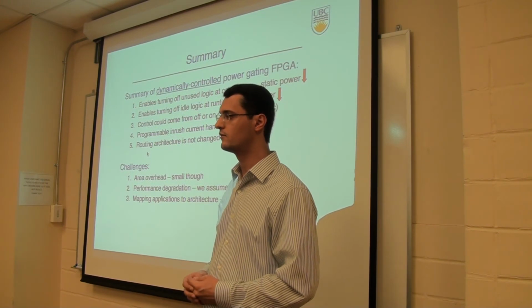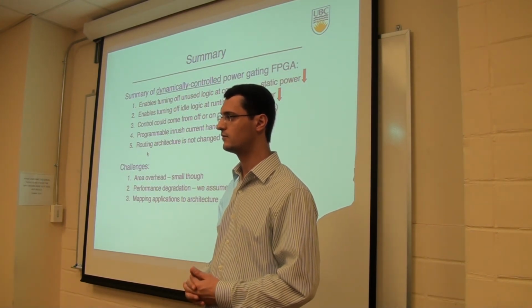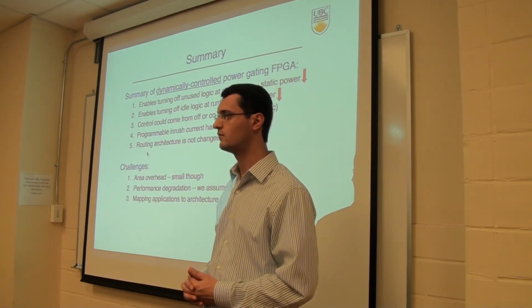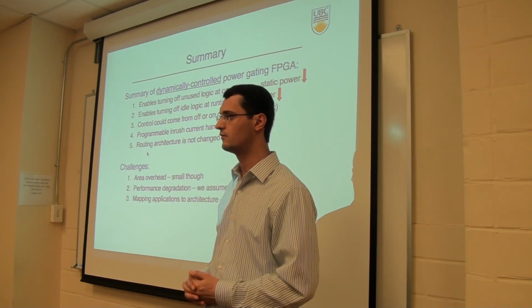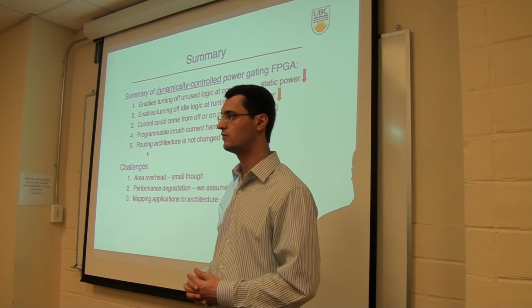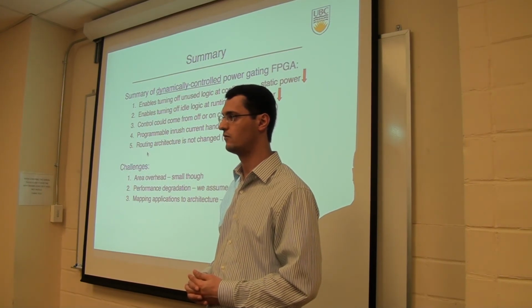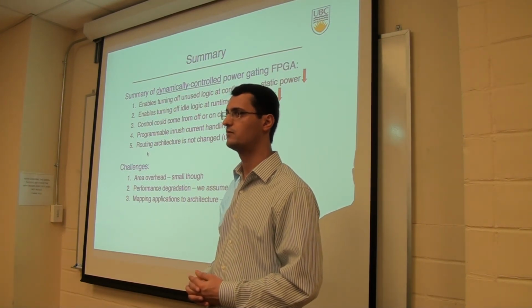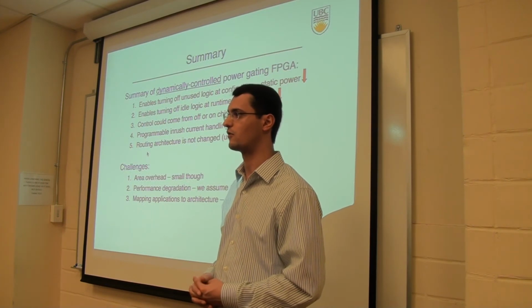Need to work it through. There's a trade-off between performance and leakage power consumption, right? Just forget prior to your work. If you want to give up less leakage, you can do it by asking for less voltage, or threshold voltage. There's a fundamental trade-off there.